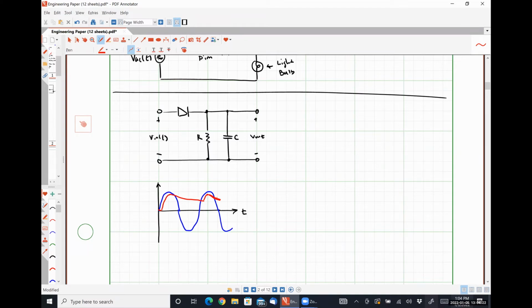So if the voltage here at this node is somewhere close to V peak minus V D on, and this guy is decreasing to less than that, I would argue that diode is now reverse biased, right? So the diode turns off, and then our capacitor starts discharging through our resistor, where that rate of discharge is governed by the time constant, R times C, right?